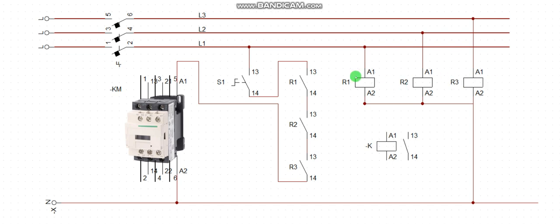So these relays, the coils are here, then the contacts are here. I just aligned them here, but each of these components will be like this symbol. Okay? But when designing, like I said before, you line up their input on one side and you align their coil on one side. So that's what I mean. This is my relay coil and these are their contacts. So you energize each coil on a different phase, then you feed them with their neutral as well, like I did this way. Then these are their contacts.